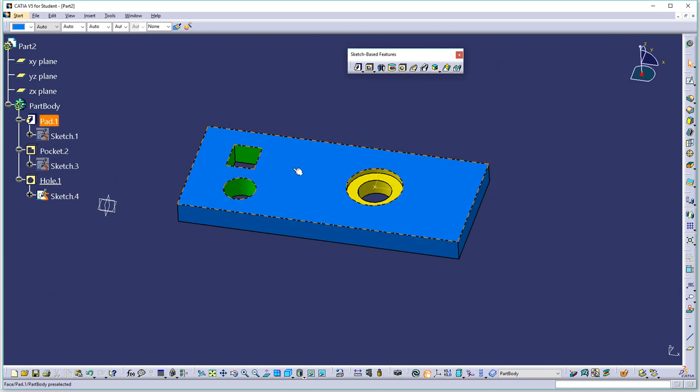Now we could maybe fake it over here in the pocket world by drawing another circle on top and having that circle come down. But on the right-hand side, when this is made with the hole command, there are machines that can actually look at this part and determine which is a hole and which is not, and it will select the right drill bit to actually make this yellow hole. So that's part of the manufacturing process.